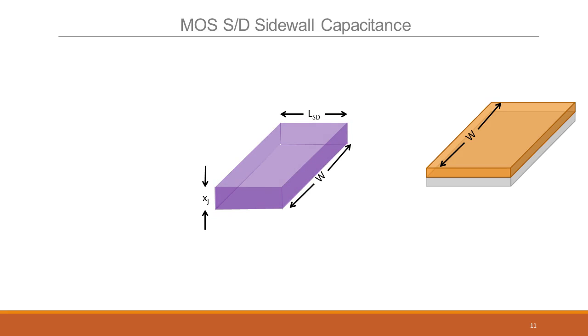Okay. Now this region has 6 faces, one on the top, one at the bottom, and 4 on the sides. And we'll study each one of them. On the top, really has no capacitance, because it's facing the air side. Air has no conduction, so the top wall actually doesn't give you any capacitance. Okay. The bottom wall, the more highlighted one here, actually has a capacitance.